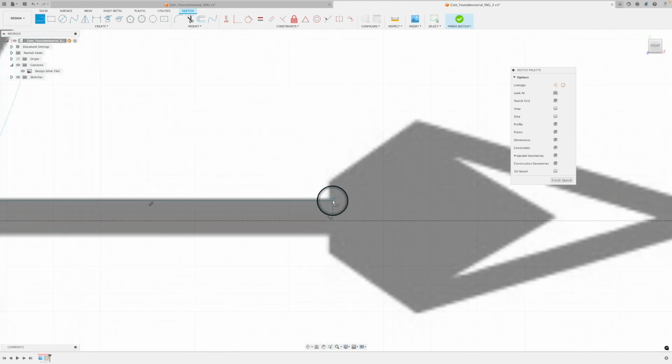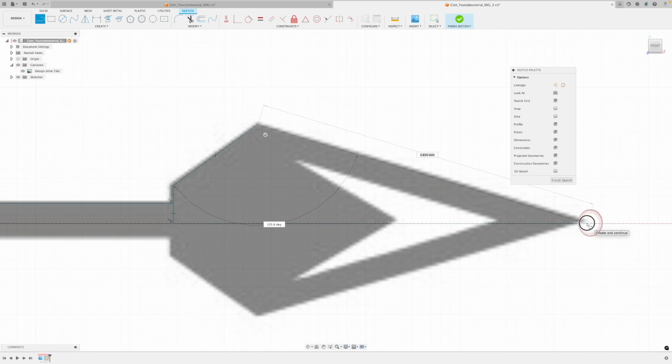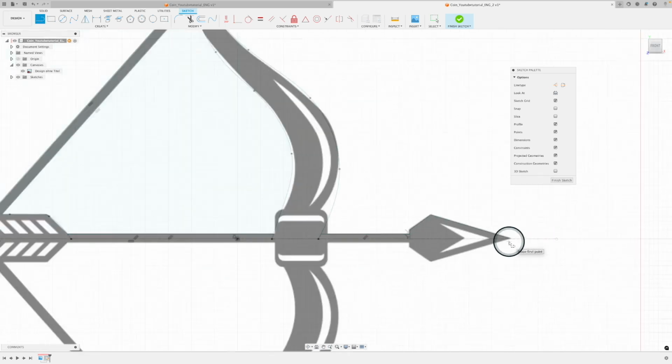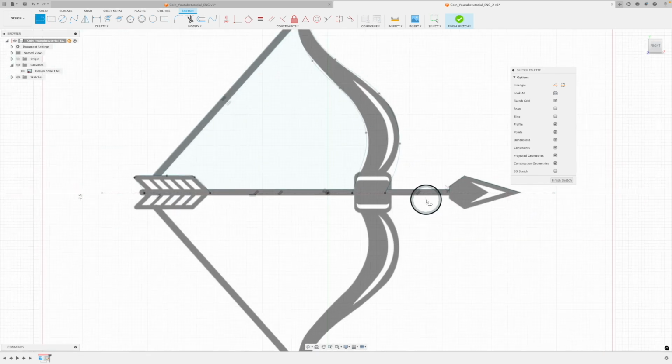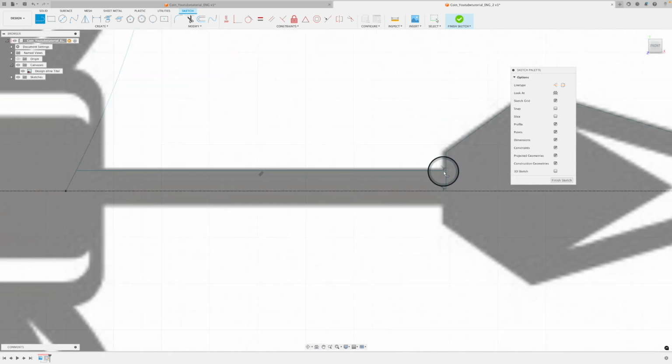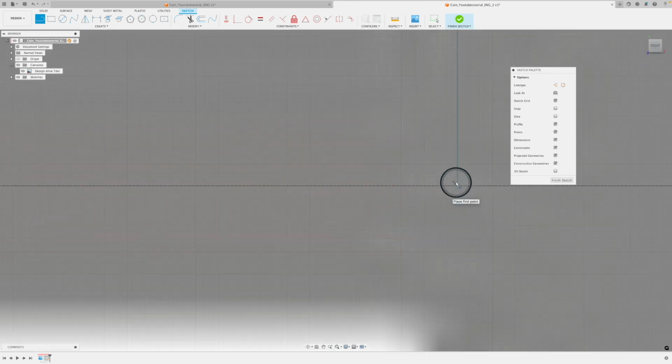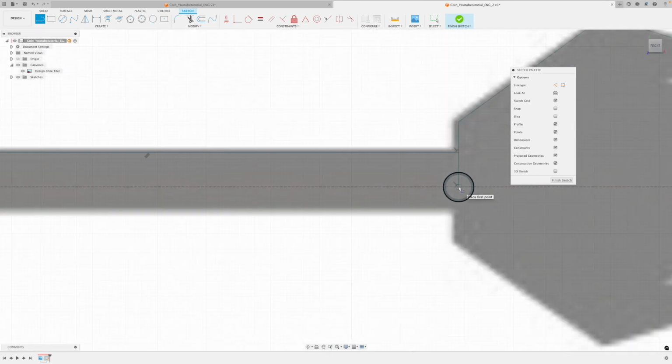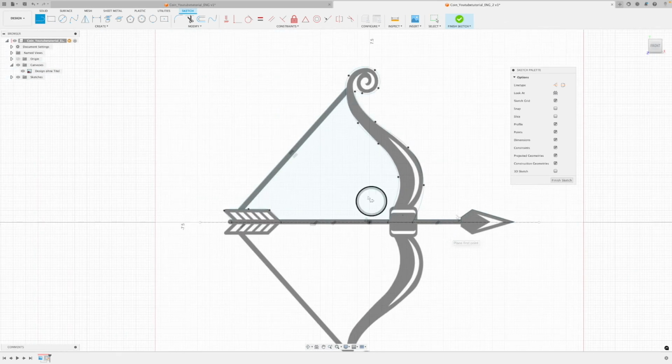And then we start on this point and draw the arrow. Okay, so once you've made sure that everything is exactly snapping on these points, and you have your point reaching exactly the mirror line, then you can mirror all these pieces onto the other side.